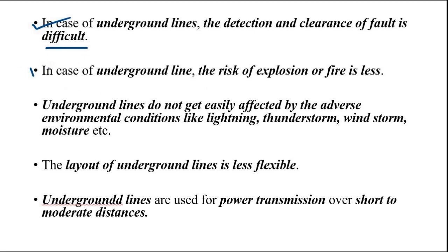Then, as it is buried, the risk of explosion or fire is less in the case of underground lines. And as it is not in the open and not exposed to the atmosphere, there is no chance of it being affected by environmental conditions. The design and layout planning of underground lines is very complicated and complex. It is less flexible as compared to overhead lines.